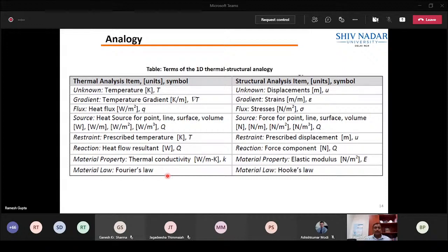Whenever you are working with any finite element analysis, people always say that you have to be consistent with the units. You should know what input you are giving, which means knowing what basic governing equations it is solving. In your terms it may be displacement, the derivative terms may be strains, and then the stress you are calculating, but internally it is looking at nodal temperatures or temperature gradients or heat flux. So this is where the analogous quantities will help you. If you make one set of program, it can be utilized in many ways.